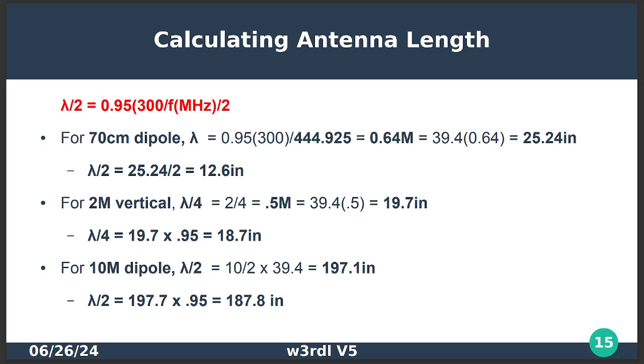If we're looking for a half wavelength, we're looking at 25.24 over 2, so 12.6 inches would be your half wavelength. And then you carry it further for a quarter. If you're going to measure the length of the two quarter wavelength legs, it would be 6.3.